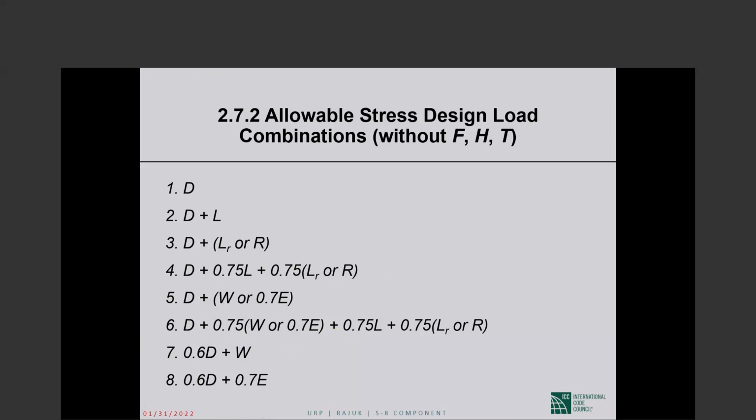Dead load causes bending moment in the same direction as the bending moment caused by wind or earthquake. Here, these are counteractive load combinations. Dead loads cause negative bending moment. Wind causes positive bending moment. So the dead load counteracts the bending moment due to wind or due to earthquake.